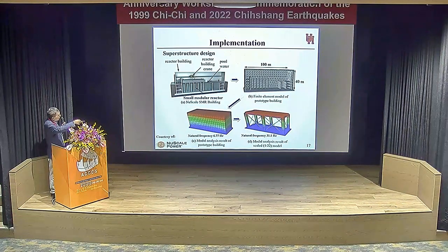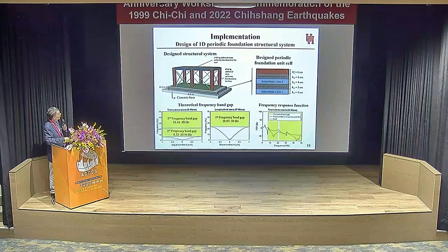We first did the modal analysis to find the natural frequency, but to use our shake table 5 meter by 5 meter, here in this lab, we need to scale down. The scale is 1 to 22, scale down. This is our scaled down design. There are 1D metamaterial foundations. We design like this one, as you can see.